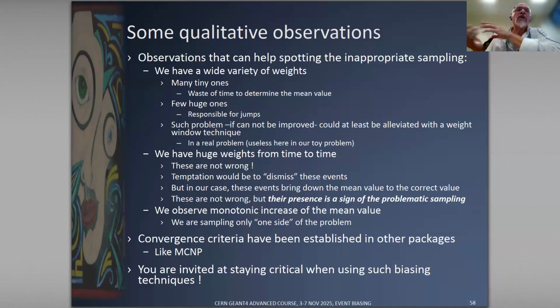Then this is where you could, for example, use a weight window technique. So in this case, it's not possible because it's too simple a problem. But then using a weight window technique will allow you to alleviate partly this problem. And the thing also with this very huge weight that we have from time to time, you have to consider that they are not wrong. That is, the temptation from time to time would be to say, oh, they are just a few pathological values, I drop them. But in fact,